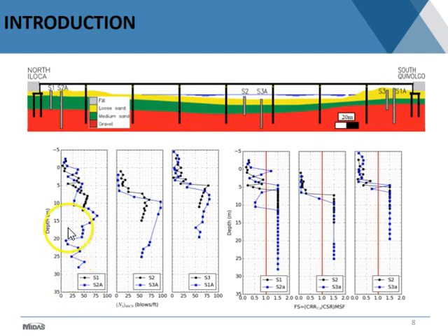So 25 would be a rather dense or medium dense sand in this condition, and you see numbers that are around that number, and then numbers that go above that. Then same thing for S2 and S3A, and a similar thing for S3 and S1A, the SPT profiles. So for this structure, we performed a liquefaction susceptibility analysis to try to identify what would be the layers that are likely to liquefy.